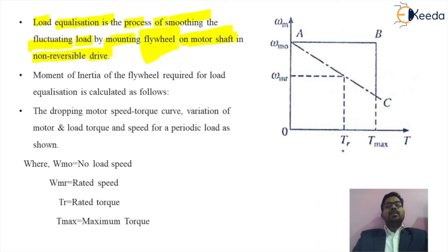If the fluctuation of load torque is reduced, then obviously the voltage fluctuation will be reduced, and the stability of your electrical drive will be improved. Such a technique is called load equalization of your electrical drive.